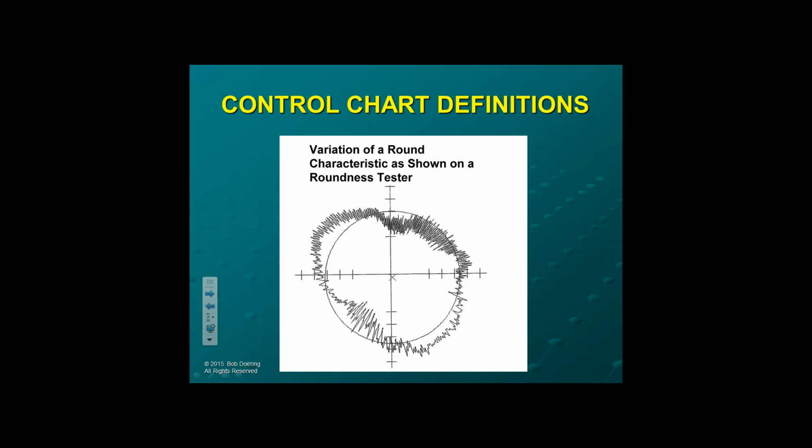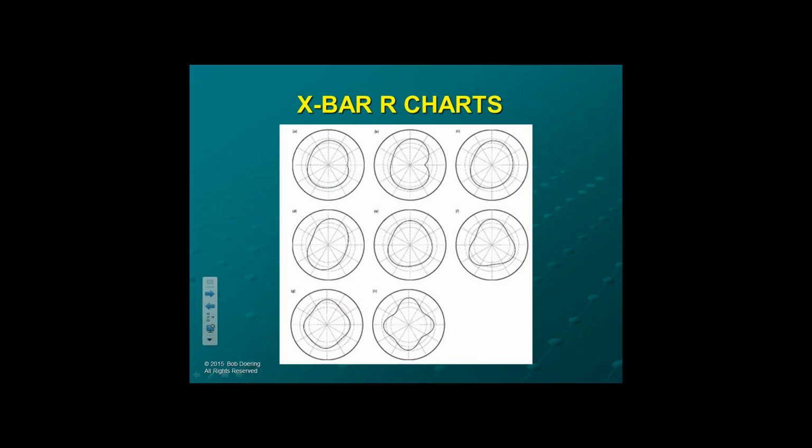In fact, if you take a look at a circular feature, you're measuring 1 out of, oh, it could be any diameter, because you have this roundness issue that's not perfect. So the real problem is, what diameter did you measure? And what does the difference in the diameters that you measured across 5 parts really represent?